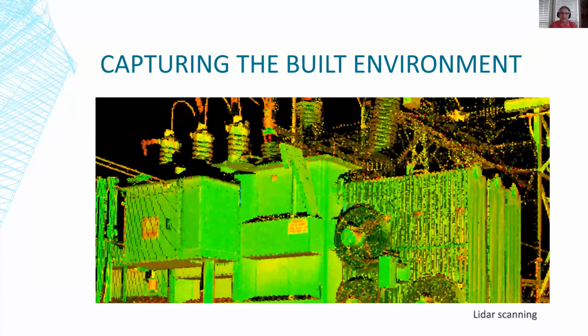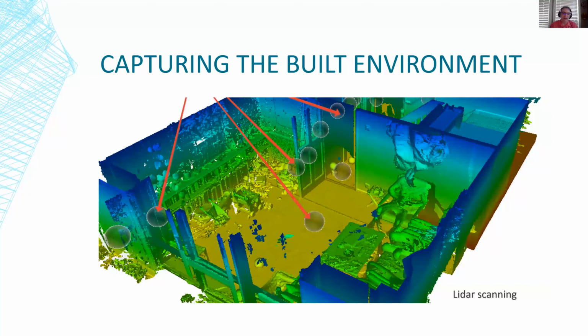The other issue with LiDAR scanning is, as you can see here, each one of these circles represents a scanning station. So you have to put your scanner down or walk around and really capture everything, because with the scanner, anything that's occluding something behind it, the laser cannot detect. And that's when you get holes, essentially digital black holes. They have to be filled manually.